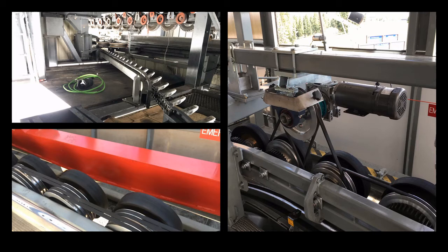The image on the right shows a spacing system for a detachable ropeway. This ensures that all of the carriers are properly spaced apart and uses a set of tires that are powered independently by a spacer motor rather than connected to all of the other tires via the PTOs. A sensor system will detect if the carriers are spaced too close together or too far apart and will speed up or slow down these tires as necessary to adjust the position of the carrier.